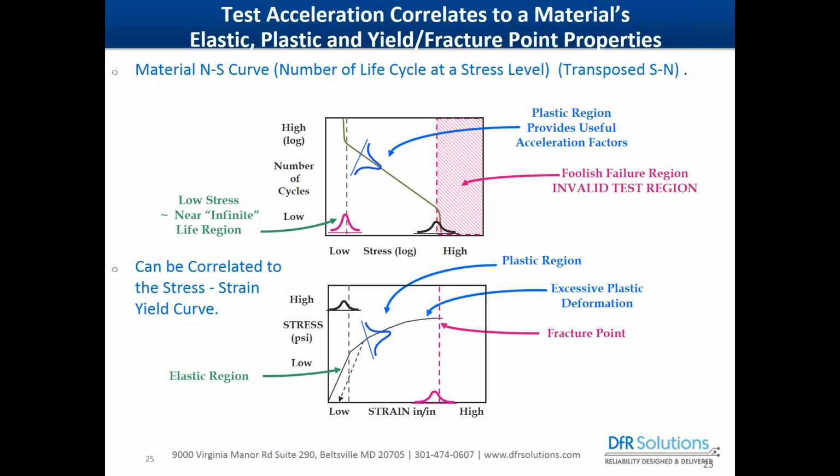And actually, we've seen this quite a bit in organizations that use the HALT, highly accelerated life test method, where you've got parts in a chamber with very powerful vibration and thermal cycling combined, and you keep incrementing the stress levels as you go through this test until failures occur. Well, when we do failure analysis of the failures on the whole test, the majority of them are breakage, overstress, fracture failures, not wear-out failures.